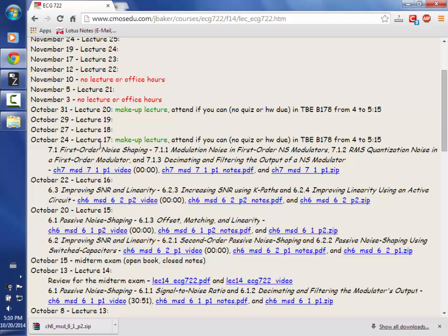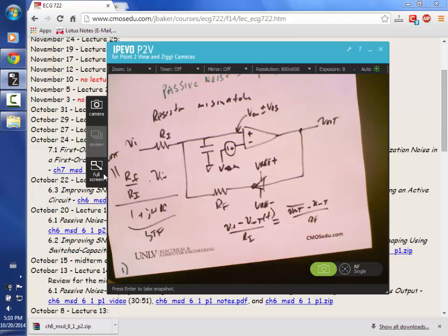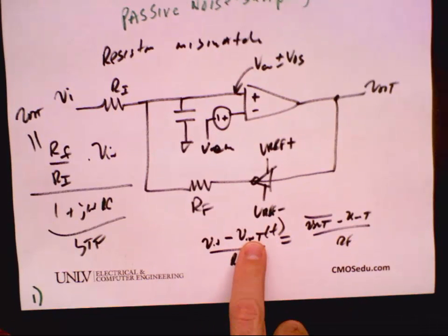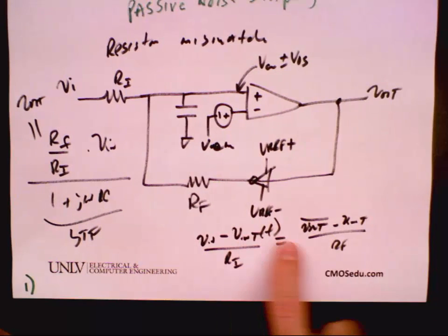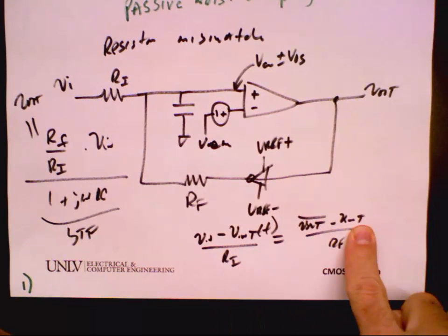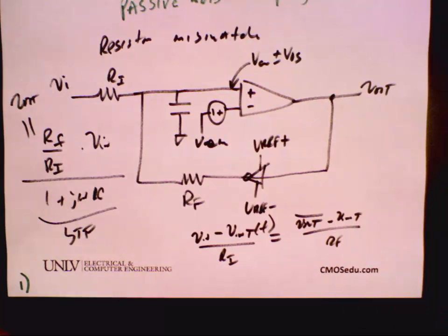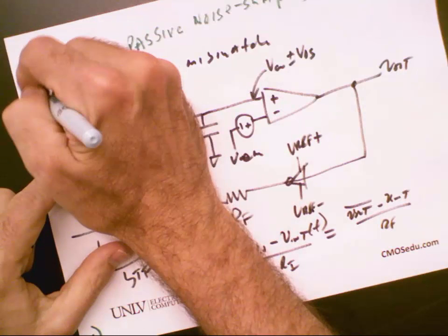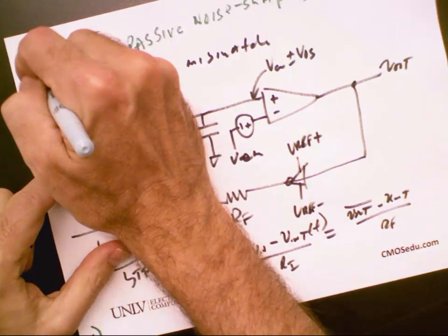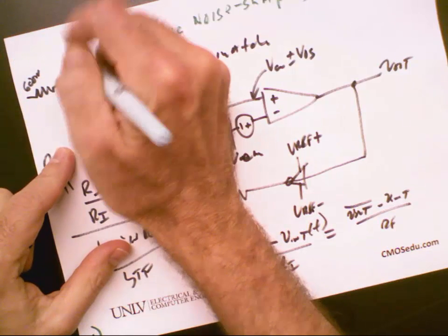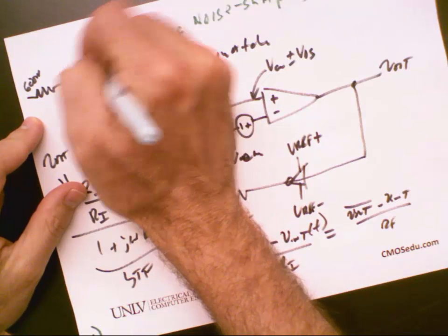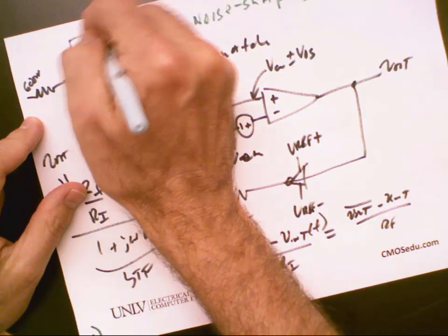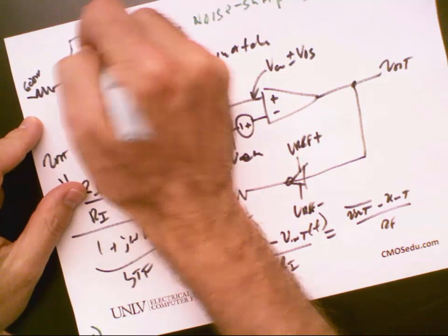No, I think it's because of this issue right here. I think what happens is that when you have the 4-bit DAC and 4-bit ADC, you can get the situation where Vin minus Vint is equal to Vout minus Vint, and it always works. So say I get 600 millivolts here, then it comes in, and this is at, let's say, 550 millivolts, and then my feedback DAC's at 500 millivolts, and I get 10K, right?